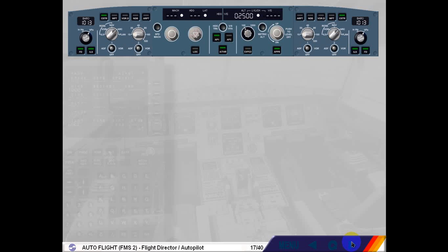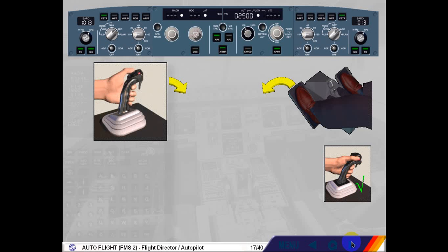The recommended technique to set autopilots off is to press the Autopilot Disconnect push button on a side stick. They can also be set to off by acting on the side stick or rudder pedals with a force beyond the given threshold, or pressing an autopilot push button on the FCU when the corresponding autopilot is on.